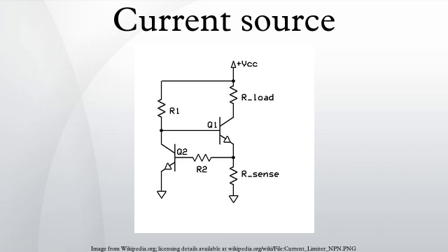Active current sources have many important applications in electronic circuits. They are often used in place of ohmic resistors in analog integrated circuits to generate a current that depends slightly on the voltage across the load. The common emitter configuration driven by a constant input current or voltage, and common source driven by a constant voltage, naturally behave as current sources because the output impedance of these devices is naturally high.